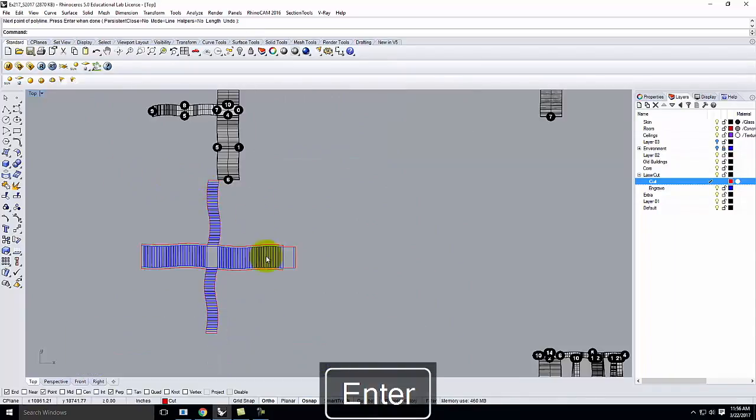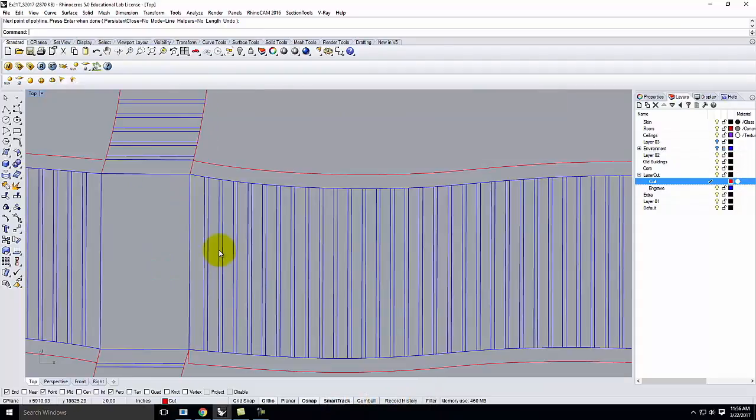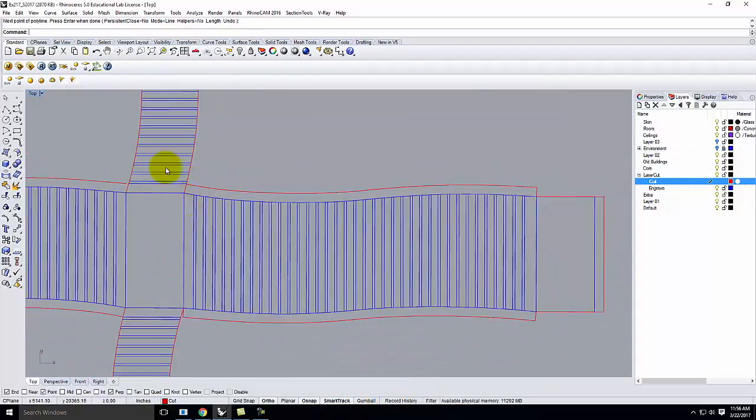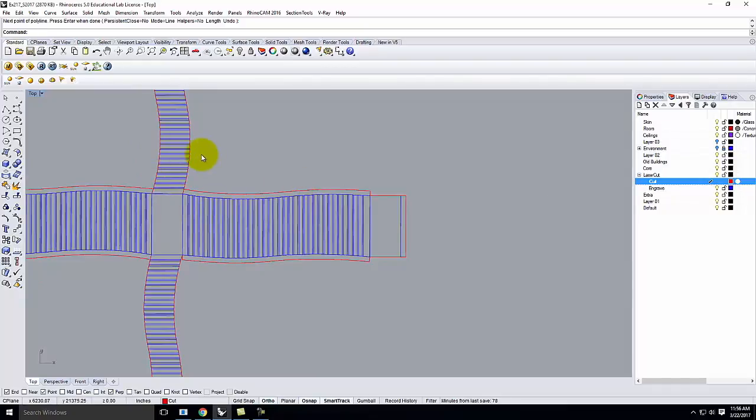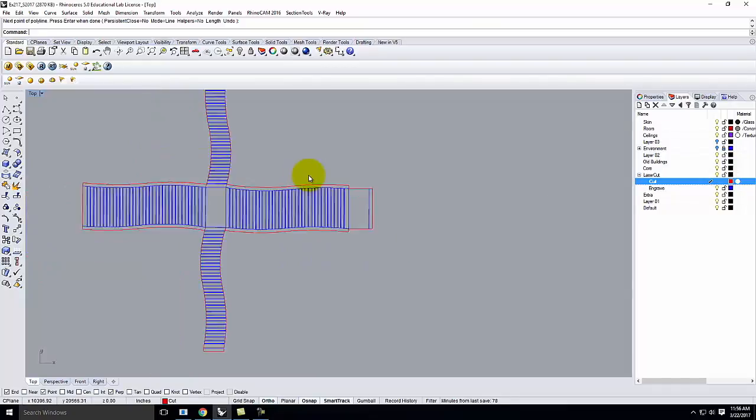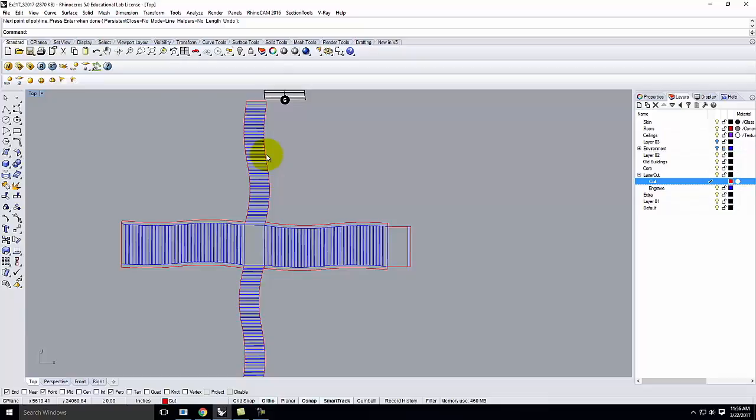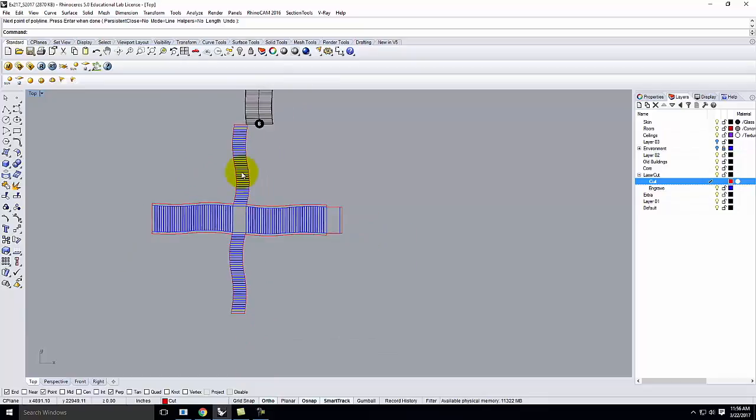And so now, this object that I created, if I were to cut it out and assemble it, the floors will line up and represent every floor of my building on the model that I create. And I'll have little glue tabs that'll let me attach and get these pieces to come together after I laser cut the file. So my purpose today is to teach you to unroll, make modifications to your building as necessary so that it will actually unroll, unroll it, and then create a file that looks like this with blue lines and red lines as if you were going to walk over to the laser cutter and cut it.